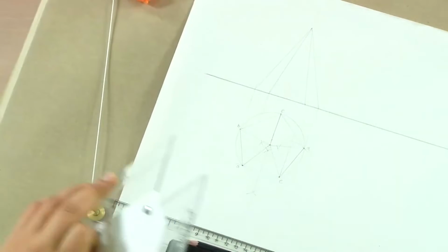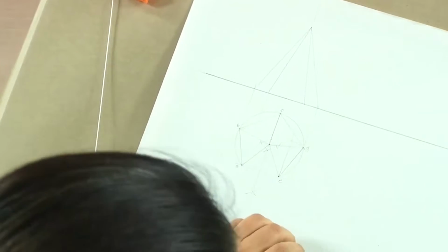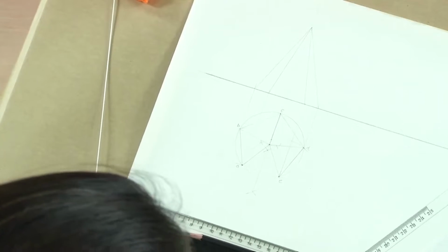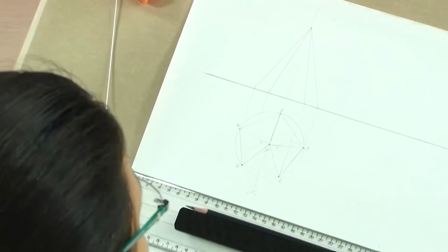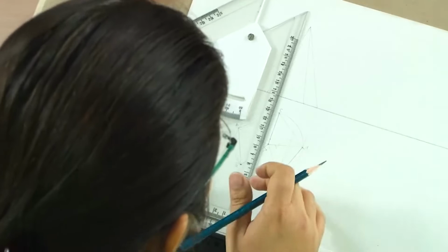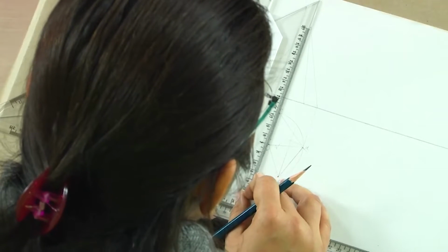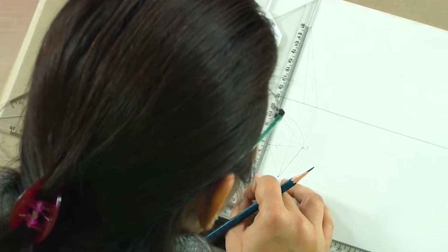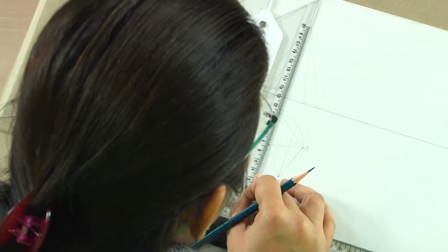Now, we assumed that there is a horizontal plane which is cutting the axis at the center. This is an 8 centimeter long axis of this pyramid. So, let us mark the midpoint of this axis, and this is the point where the section plane cuts through the pyramid. So, this is where it is getting cut from.